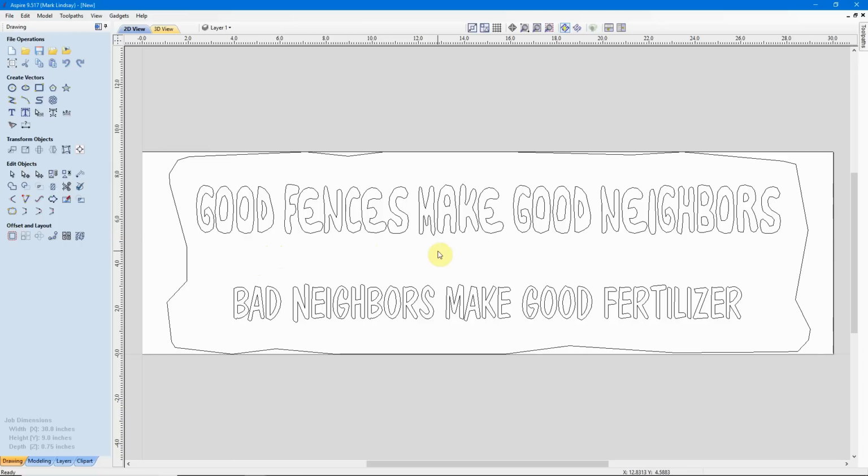The takeaway from this is that you can convert a standard font text to curves and manipulate those curves, modify, change them. You can get in and move things around, change spacing, everything using the standard vector editing tools once you have converted them to curves. However, when they've been converted to curves, you can no longer use your text editing.